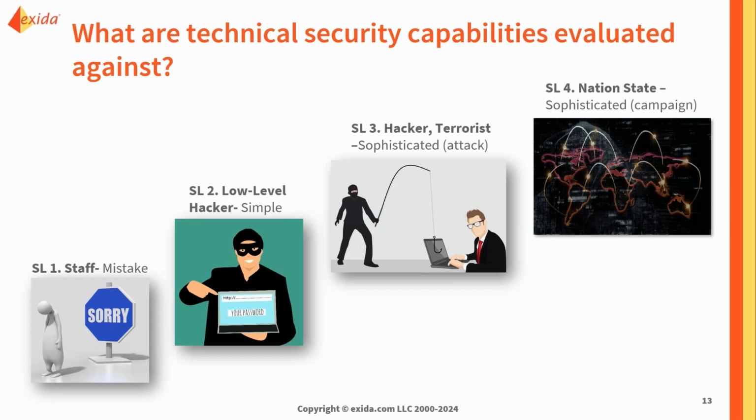And really, depending on the risks for that site, the target of what security level they need to meet may vary. If there's a less critical system, SL1 may be all that's required, for it to implement a number of best practices and a really good starting set of robust requirements for cybersecurity. Whereas for other systems, let's say they're critical safety systems or critical control systems, they may have significant risk associated with them and may need to, say, target security level 3 and have the additional requirements involved to meet that higher level.